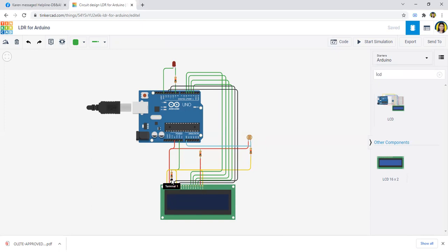Resistor terminal 1 must be connected to the contrast, and your resistor terminal 2 will be connected also to the read and write, and then it will be connected to another resistor connected to your photoresistor terminal 2. In that case, the terminal 2 of your photoresistor must be connected to the A0 of the Arduino board.